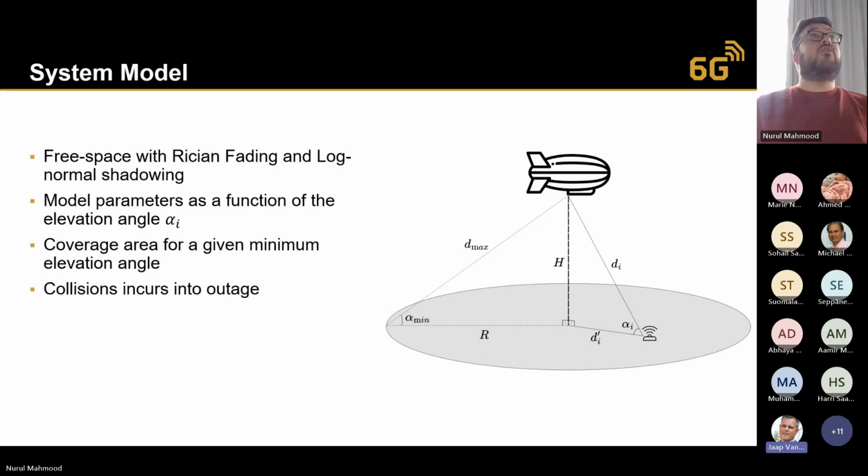So the header takes 233 milliseconds, and then the payload fragments are 102 milliseconds each. One hop per second also? No, actually more, because for each header it transmits the header and then hops to another channel, and then transmits another header, and hops. So for each 233 or 102 milliseconds, it keeps hopping.